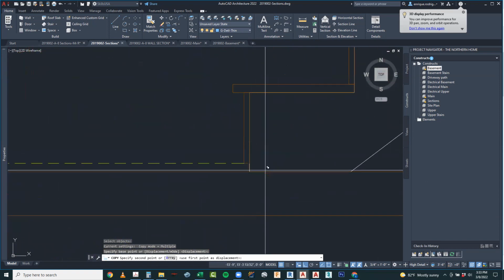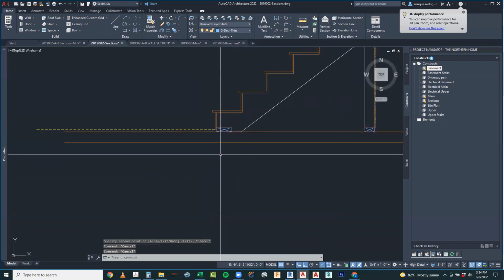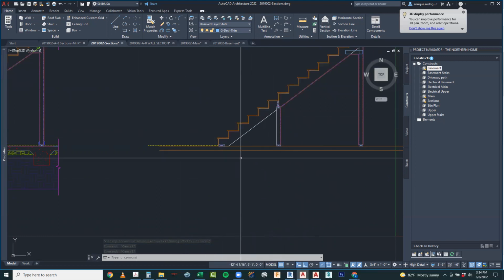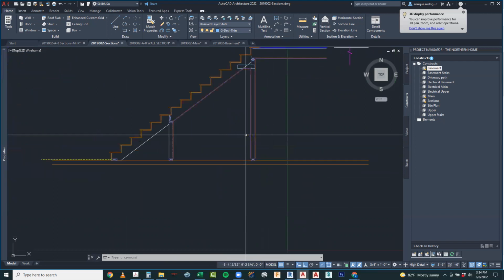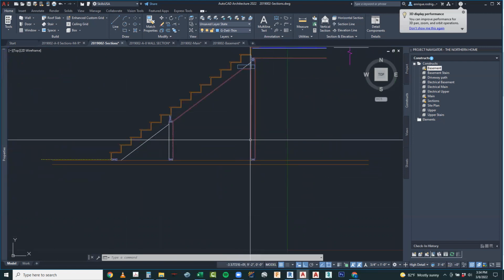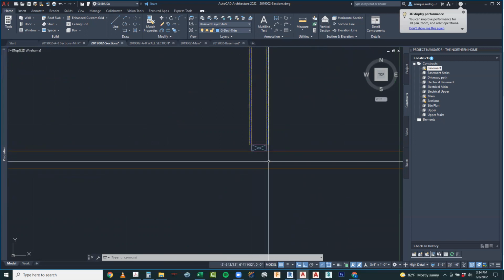We want to place it down here. This is what we call a kicker. It actually stops the stair stringer from sliding this way because this is anchored to the slab right in here. Now, the one thing I did mention is that this is a bearing wall. That means it's putting a lot of load and pressure right onto that slab, and it's only a 4-inch slab.